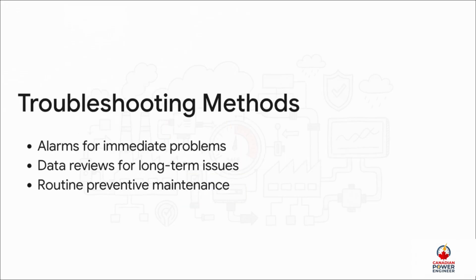To prevent this kind of catastrophic legal failure, control rooms rely on a massive web of alerts. Immediate problems, like an analyzer pump suddenly failing, a sample line clogging up, or a core computer crashing, trigger urgent alarms demanding instant operator intervention. Meanwhile, continuous data reviews highlight those slow, sneaky, long-term problems, like a steady sensor drift. This is exactly why routine preventative maintenance, like regularly scheduled calibrations and smoothly changing over redundant equipment, is absolutely vital to keep that data quality assured.